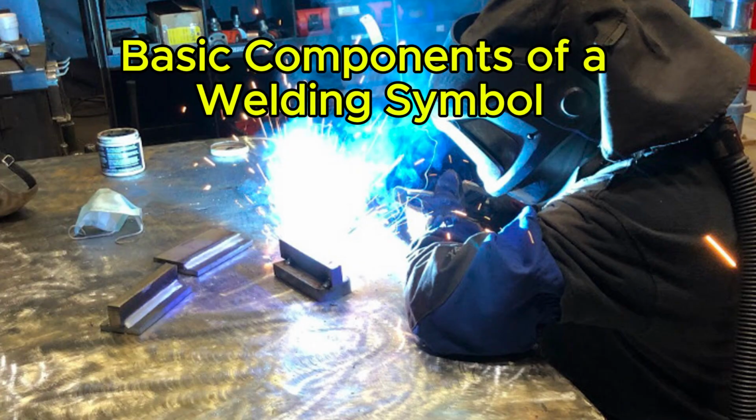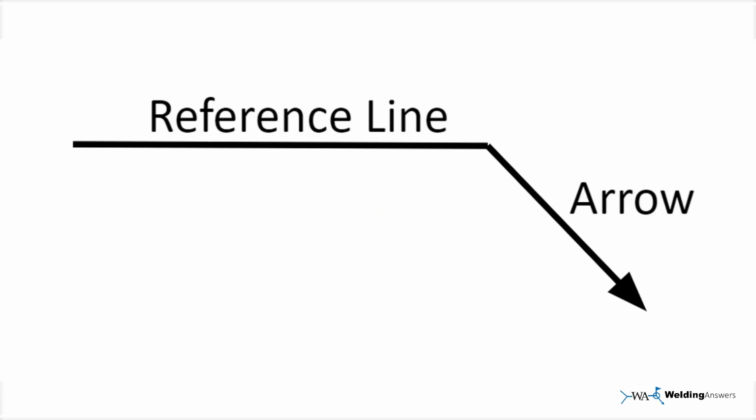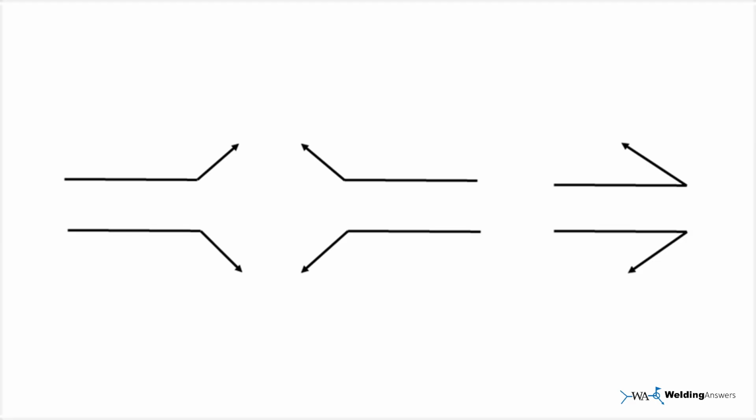Basic components of a welding symbol. Every welding symbol at its core has two basic components, an arrow and a reference line. The arrow points directly to the location of the weld on your drawing. The reference line, on the other hand, is where all the crucial information lives. Details like the type of weld, its size, and other important specifications. You'll notice that the arrow isn't always pointing in the same direction. This is perfectly acceptable. Its orientation varies simply to fit the symbol neatly within the available space on a blueprint or shop drawing. All the variations you see here are correct.